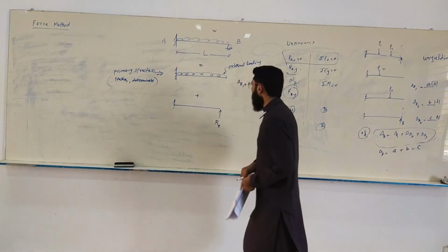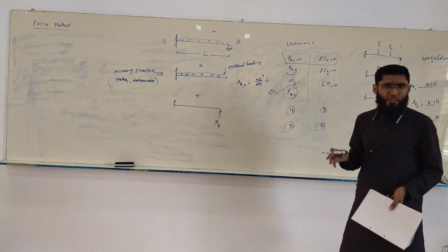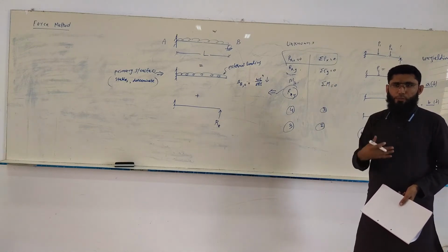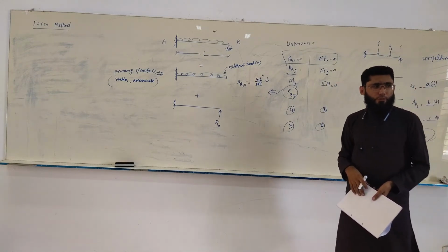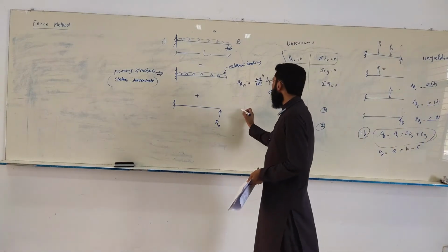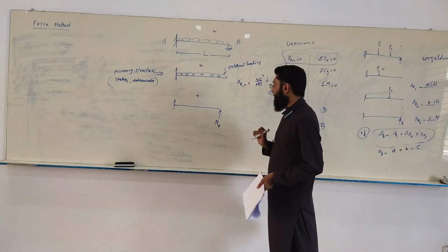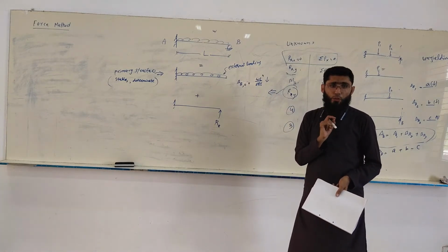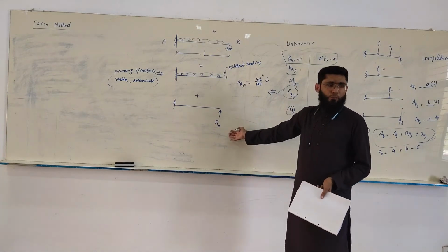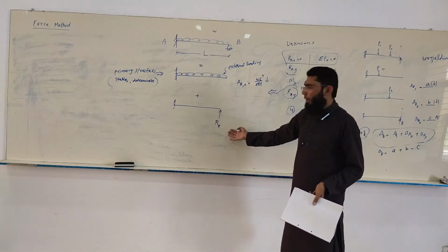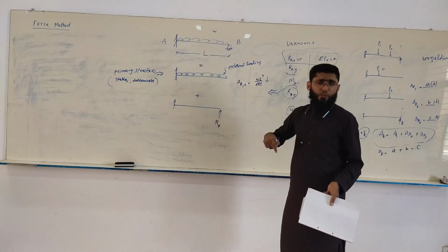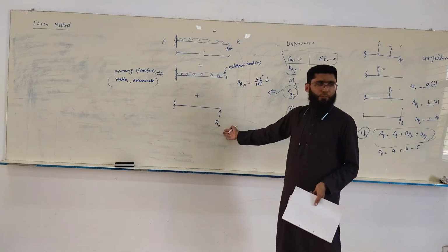So in this course, in the exam, you are allowed to bring these tables where you can see the ready-made formula for calculating the displacements. Okay. And the displacement over here, we do it in a further simpler way. What we do is, RB is an unknown. So even if you try to define the displacement at B, it has to be in terms of this unknown RB.